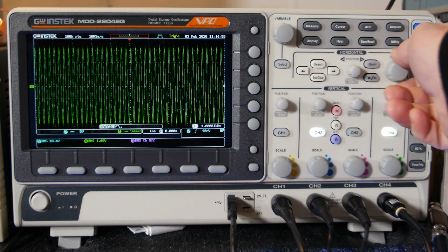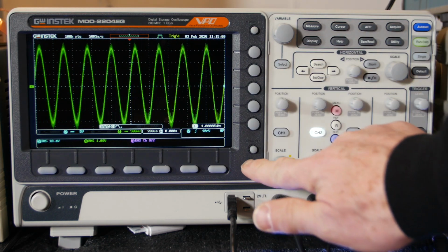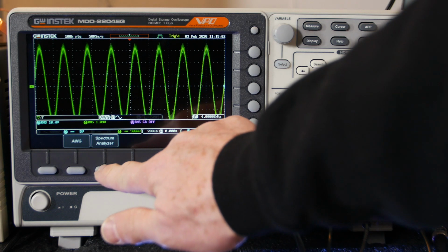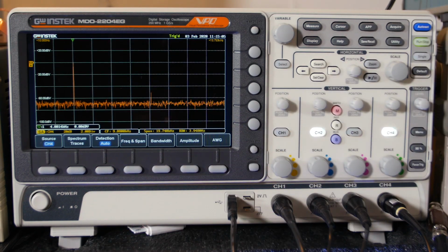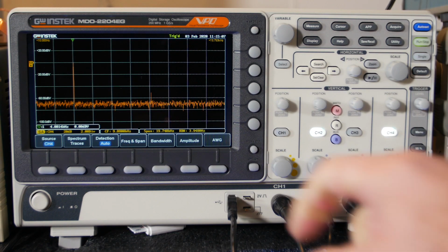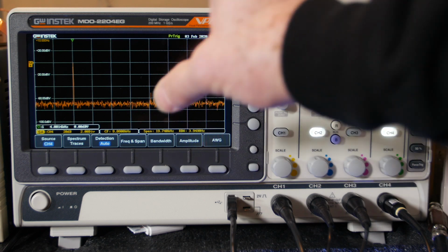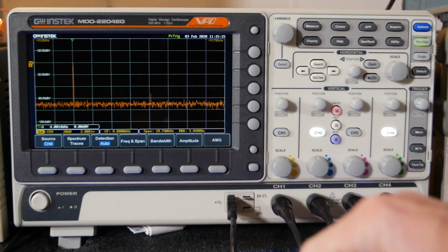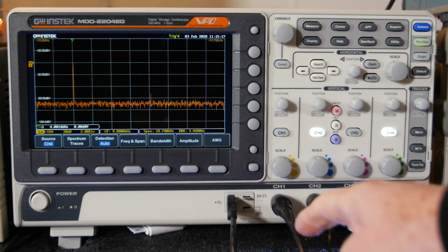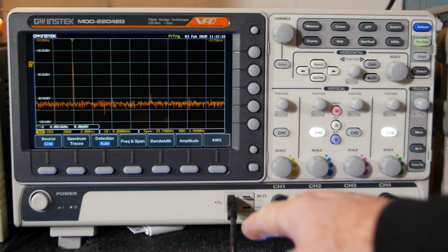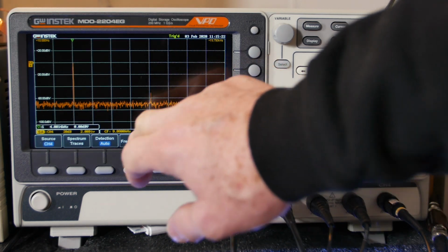And adding cycles like that, I'm not sure if it made a difference. Let's see if it did. Let me get fewer cycles and see if that makes a difference. No, it doesn't look like it really changed the measurement. But I think in spectrum mode, it does its own thing. I don't have to capture all those cycles. In FFT mode, you do, so you've got to be careful about that. But yeah, there's a little small signal there now.